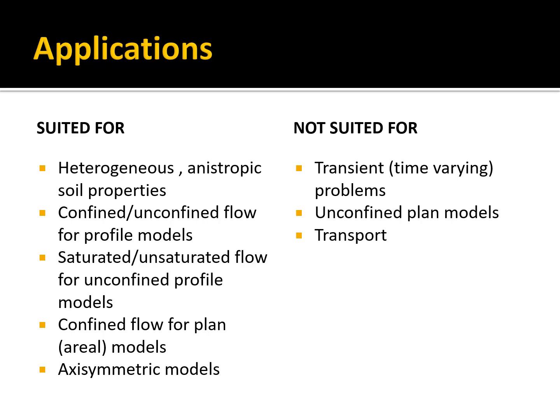You can also use it for confined flow, for plan view areal models, or axisymmetric models like flow to a well. But we're not going to cover those this semester. We're just going to do profile models. What it's not suited for: it doesn't do transient or time varying problems. It only will give you a steady state solution, or unconfined plan models, or contaminant transport. But it's great for profile models. Super easy to use. Really great tool.